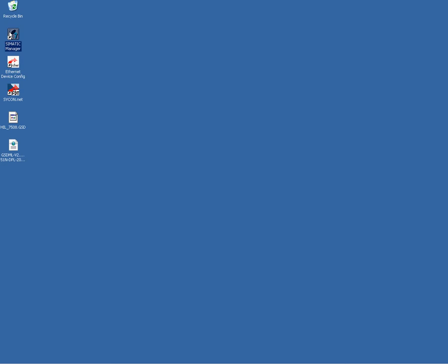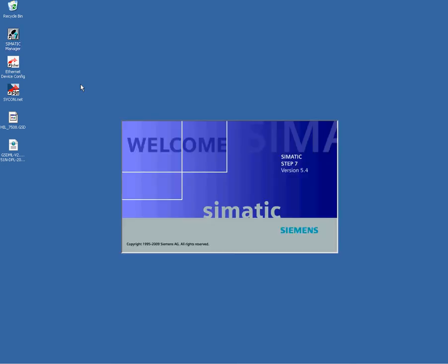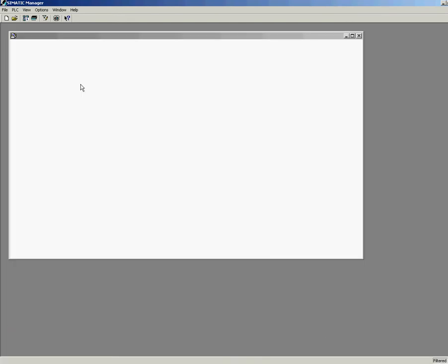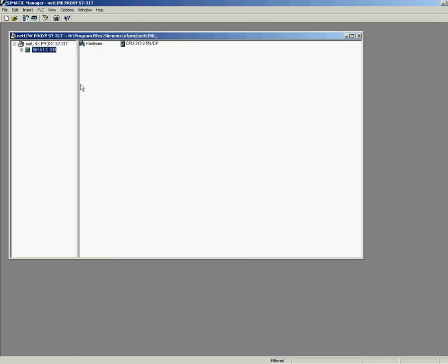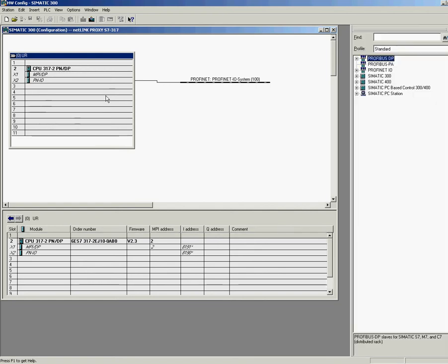As next, I start the Step 7 software from Siemens to configure my PLC. I have prepared a tiny little project already. In order to configure Profinet, you have to click on the PLC and choose Hardware. Then the Hardware Configurator will open. Look, you see already some devices configured, and one of them is the Profinet I/O controller with its empty bus line. What we have to do now is to import the GSDML file that I have exported previously within Cycon.